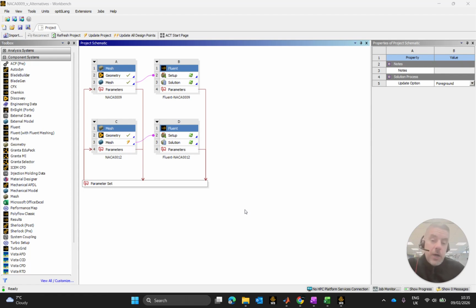Now, to get the geometry for this, I'm just going to do the exact same procedure that I did in video 2 of this series, which is go to Airfoil Tools and generate in the airfoil plotter my coordinates onto a CSV file, cut out the coordinates of the CSV file, paste them into a text file, open up Discovery and bring them in there, fill it and region it.